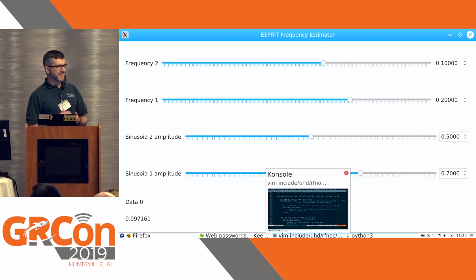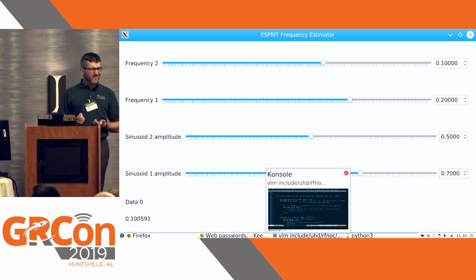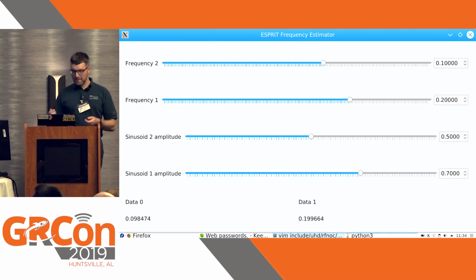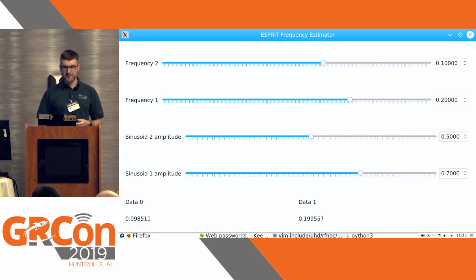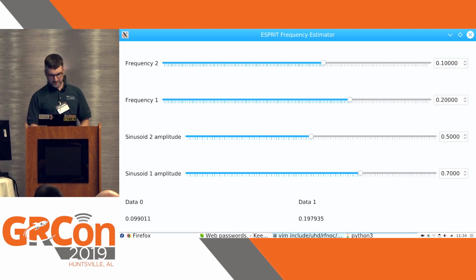This is kind of unexciting. If you look at it, you feel like, well, it's just boring. Those are just numbers. But that's exactly what you wanted. My model of the spectrum was not a plot of x, y. It was a set of numbers. So here's your set of numbers. So this is actually a legitimate frequency estimator. Maybe it's just not what you might think of when you do that.